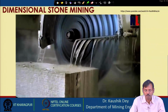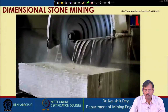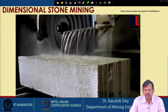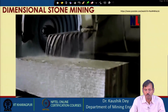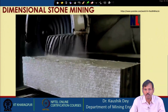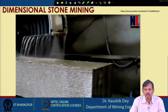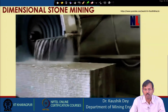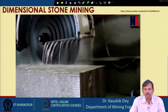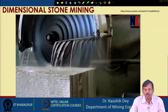Water needs to be sprinkled during all the cutting, whether it is by diamond saw or chain saw or diamond wire. Every time water must be sprinkled on the cutting device for basically two purposes. One is to dissipate the heat. During the cutting heat is generated, and on overheating the diamonds may be lost, the chain may cut. So, to avoid that, cooling of the tips is required. So, that is why water has to be sprinkled, that is the first purpose.